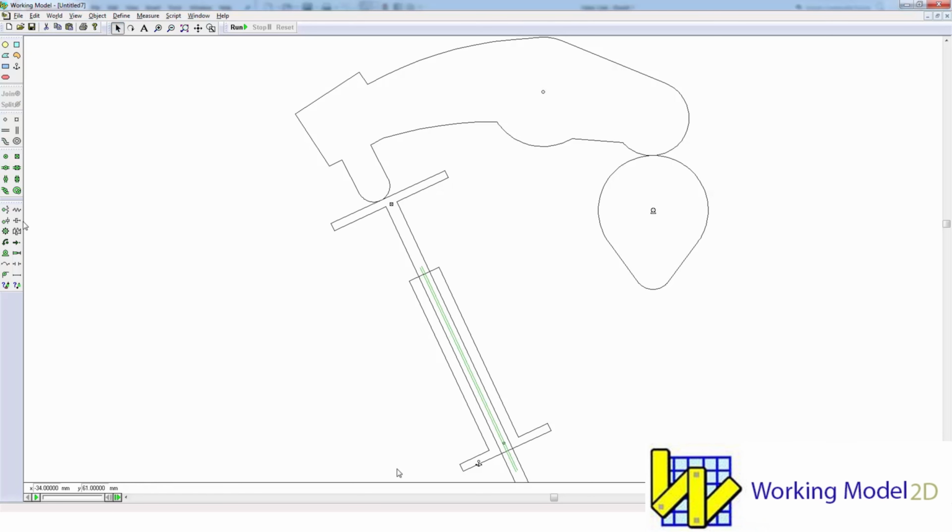Now we'll go ahead and add a spring element in between the valve and the valve guide. You can envision the spring resting on this bottom surface here, so that's why I'm using the midpoint of what that circular surface would be in 3 dimensions.